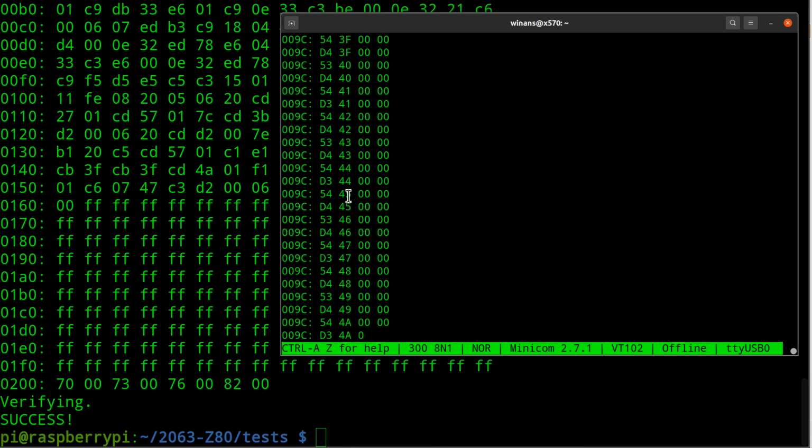These values, if I pause it, look at this thing. 53, 43, and so on. And then it goes to D4, and then it goes 54, D3, 54, D4, 53. So it's like D3 or D4 and a 53 or a 54. What we're looking at here is it takes so long to print this that when the counter advances, several interrupts pass by between the time the logic asks is it a multiple of hex 40 and the time it starts printing. It's already moved all the way up to 54. That's because of how long it takes to print this.